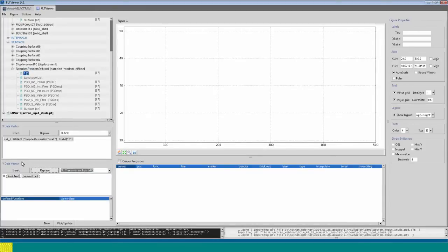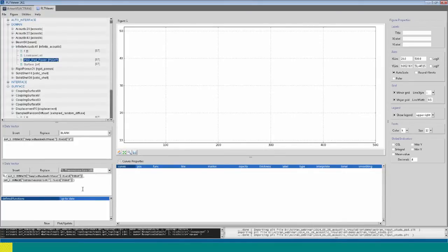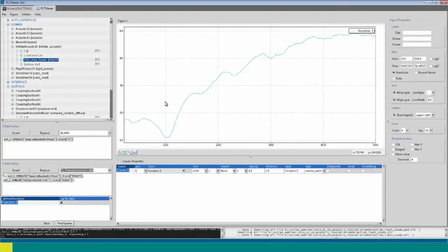It takes two terms: the incident power that I will get from the, as you can see, the sample random diffuse field, okay. And the transmitted part will be found in the infinite element domain through which the acoustic radiates. So we get the random power evaluated through the infinite surface. Okay, as I plot, we see a very typical curve of transmission loss, which is described in dB. So on the vertical axis we have the dB values, and then through frequency it changes.